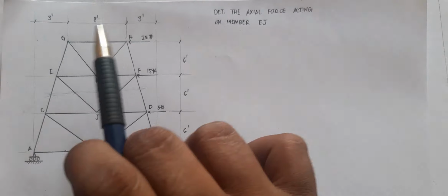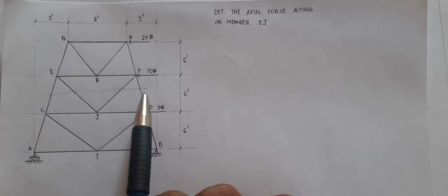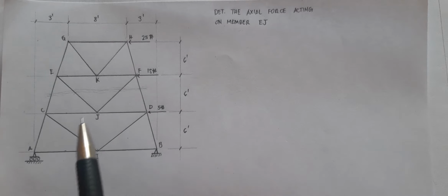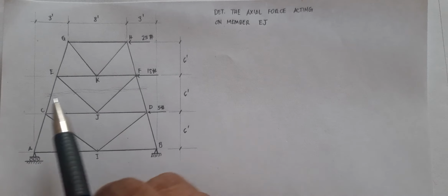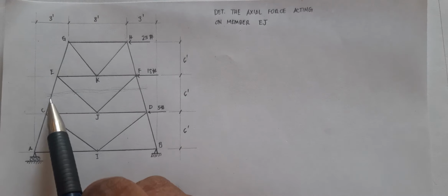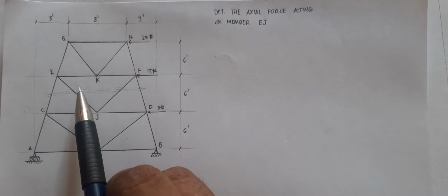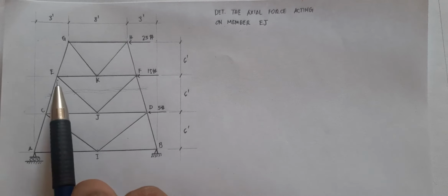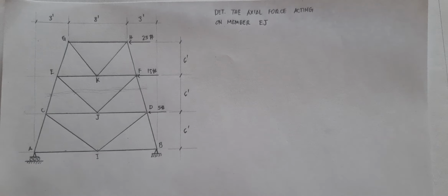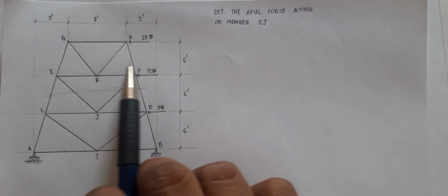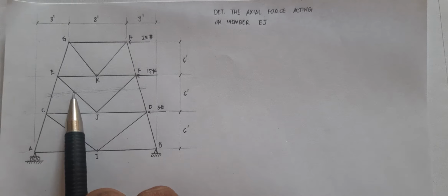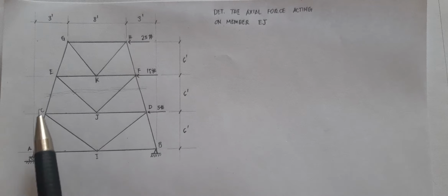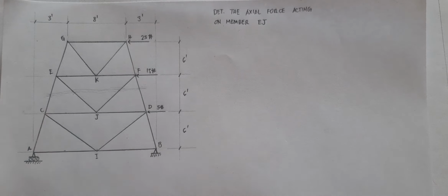So if you were to utilize the upper section using this section, then you would have a moment equation wherein that is your point of moment. You have two unknowns, CE and EJ. Now if you know the value for CE, then you can calculate the value for EJ. So the first thing that we need to do is to determine the value for CE, such that the moment equation at point F can be our solution to determine the value for EJ.